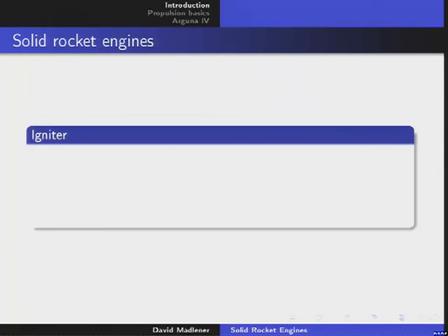let's get to the igniter. So the igniter is normally electrically triggered. Nobody today uses a fuse with matches, okay? It's logical. But you need a safety protocol. You cannot just install an igniter and think that your computer will do fine, okay? You have to have some switches to short-circuit the igniter, and you have to open them manually, not by computer, okay? And this has to be followed by a protocol.